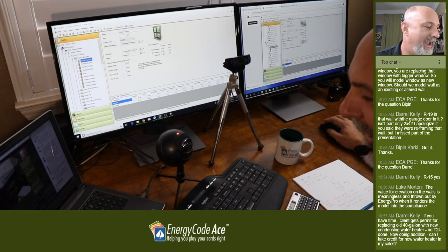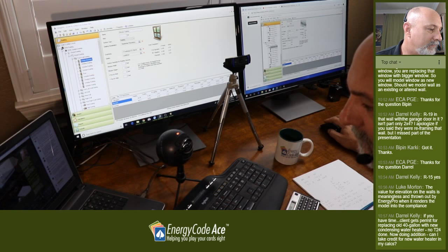So Daryl says, if you have time, clients get permits for replacing old 40-gallon water heaters. I would assume an electric water heater. No Title 24 done. Now doing addition. Can I take credit for a new water heater? Yeah, Daryl, you could, if that water heater was being replaced as an alteration, permitted at the same time as this other addition and alteration.